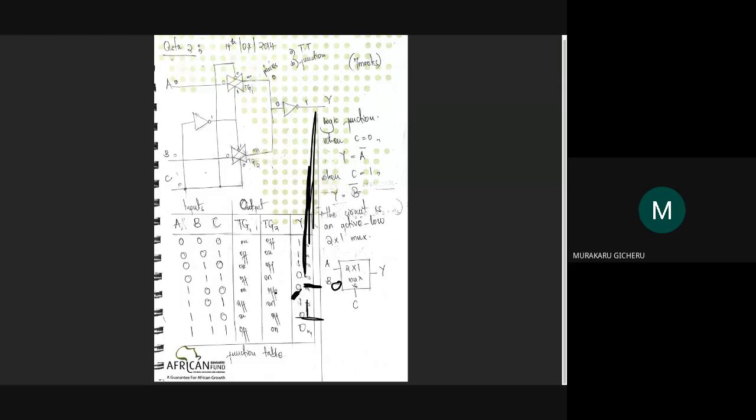So you remember how when you have this bubble, it means that when this control switch is connected to ground, that's when the chip is enabled. It works in reverse. The internal circuitry is a wire and then there's an inverter.